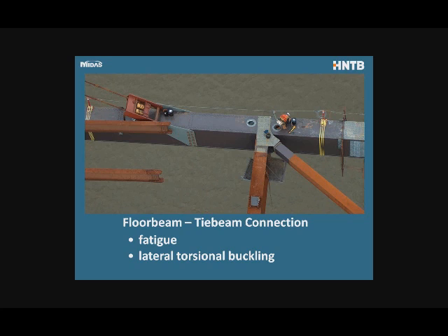And the other problem or the other advantage, so let me put it this way, so for that reason we connected the floor beams to the tie girders, and it had another advantage, which is with these long beams that are sensitive to lateral torsion and buckling. By holding the floor beams near the ends, we actually improve the lateral torsional buckling resistance of these floor beams.